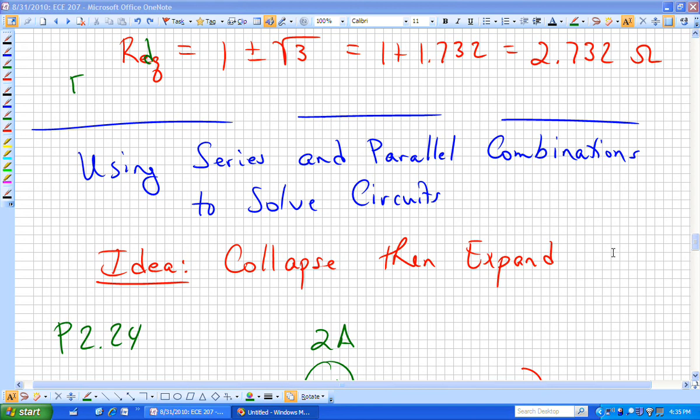I sub 5. Is anything else leaving node 3? I sub B is leaving with a minus sign. We could do it that way, couldn't we? Or we could say it's coming in, so it equals I sub B. It's however we want to do it. We could say I7 plus I5 is equal to I sub B.